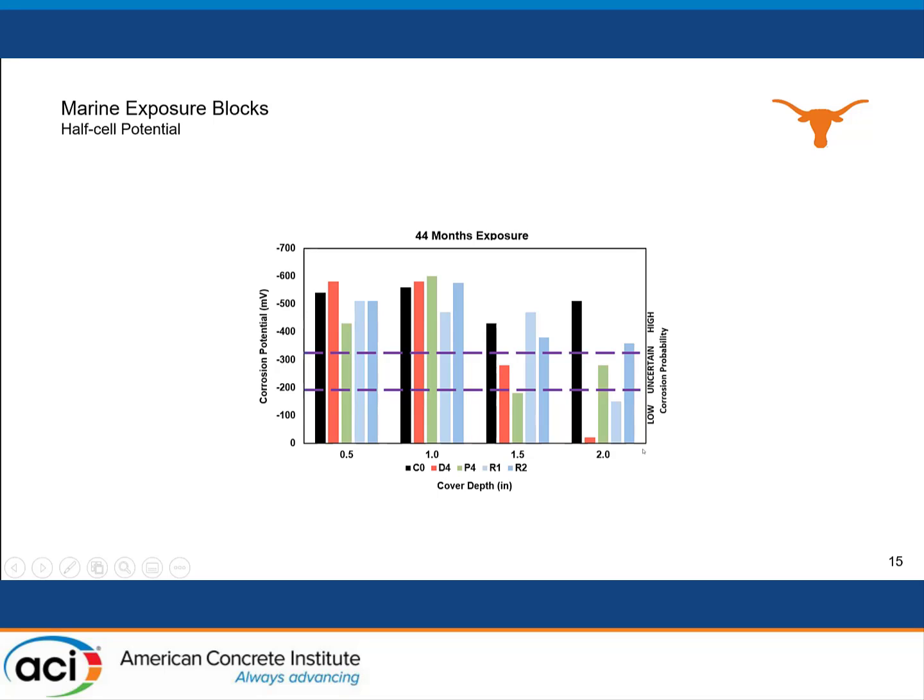And really, that's where we're going to need more time to assess what's going to happen 8 to 10 years down the line, which is more or less where I think the more important results are going to come out. And again, most structures are designed with a 2-inch cover, so the interesting results will come over here. But in the meantime, we see that our control is failing within 3 years.